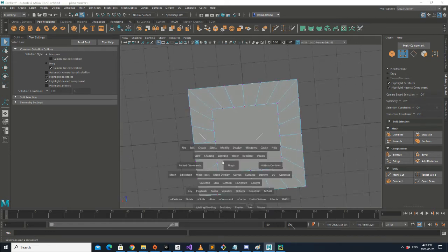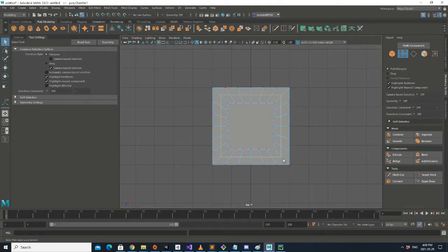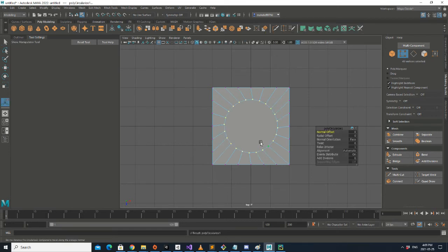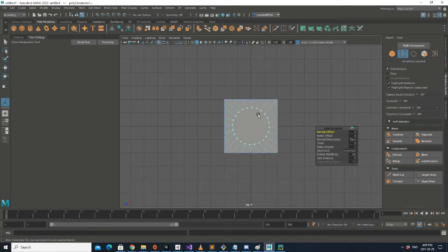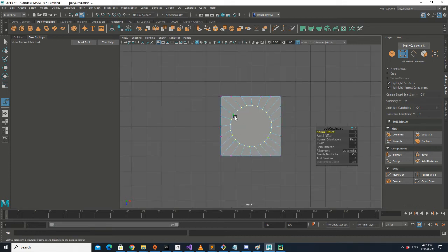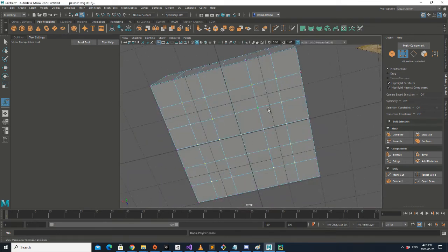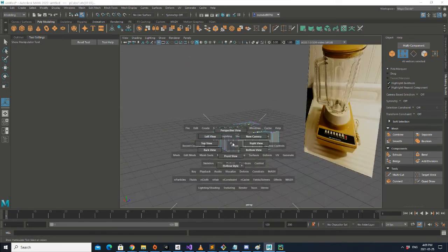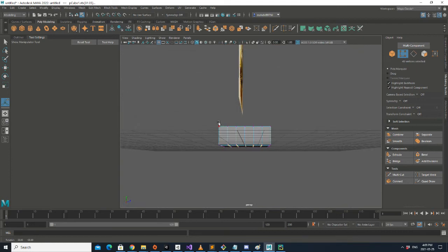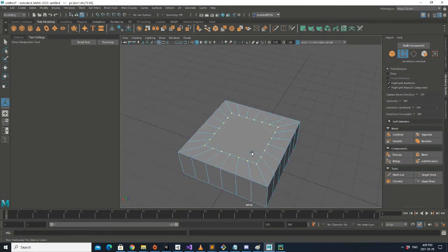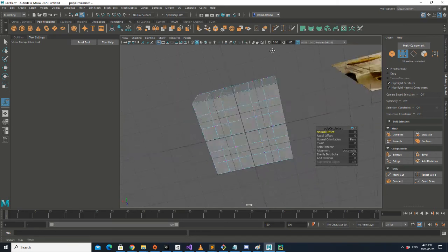What I'm going to do is go to the top view and then select all the vertices. There is one nice tool here, which is circularize. When you click it, it will make a circle for you. You can see all my faces over here have exactly 4 vertices, which is really great. And now I also have my required circle here. Oh, I don't know what I did here. Okay, yeah, that was my mistake. So make sure that you don't select the vertices at the bottom of your model. I made this mistake, and then make your circle.